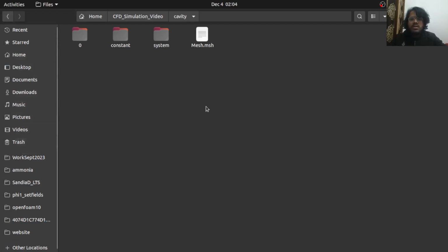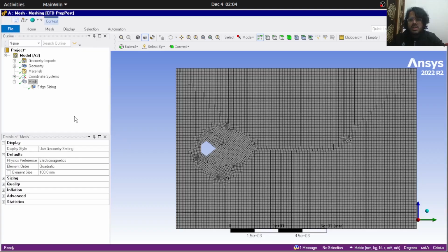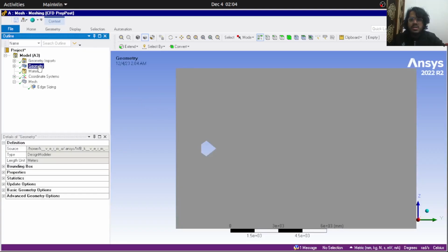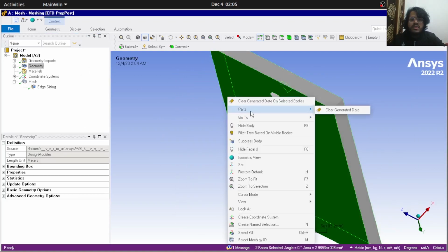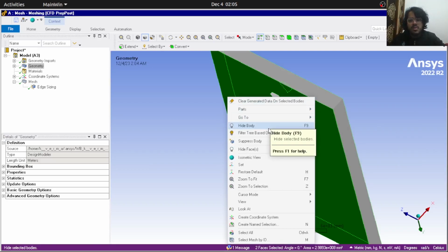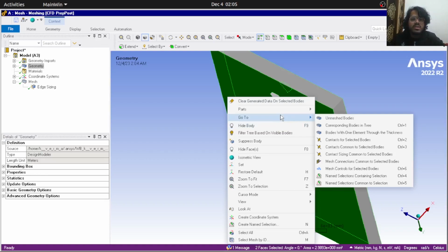After moving to the simulation part, there is one thing left in the mesh file, that is patch formation. Let me start with the patch formation. This will be the front and back part, as we will be using 2D geometry in OpenFOAM. Actually 2D geometry is 3D, but in Ansys software you just need a surface to do the 2D simulation, but in OpenFOAM you need a 3D case with no elements on the thickness side. Okay.